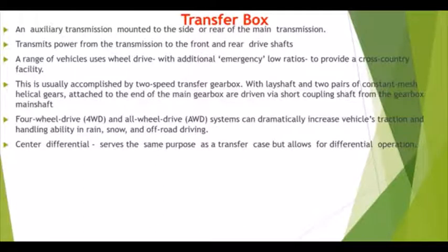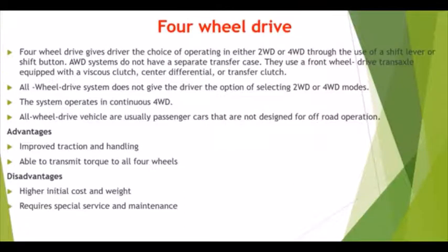There is also a traction controller which we use in the case of two-wheel drive apart from the differential, with which you can run your vehicle in skidding areas or in mud, as it provides traction to all the wheels, can lift the load, and can supply the power equally. That is a different topic. Keeping it aside, let's move on to the transfer box, which we call a central differential, whose major purpose is to transfer the power to the differentials. That is the major operation of the transfer box.